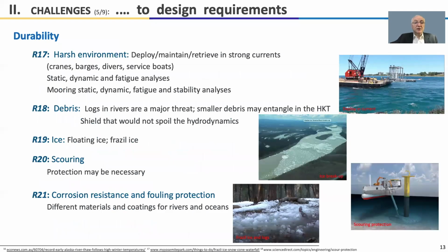Under durability, you know that we have to operate in harsh environments, which is probably fine. That's what we are designing for. But on the other hand, we have to do the deployment, the retrieval, maintenance, redeployment. These are very difficult operations. Sometimes we may even have to use cofferdams. But we also have to conduct static, dynamic, and fatigue analysis, and same thing for the mooring system.